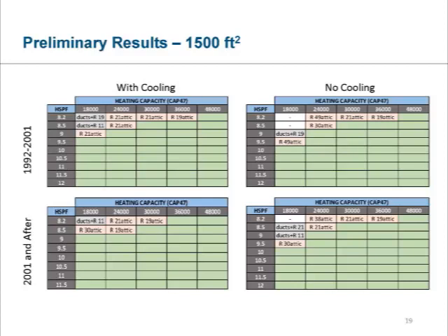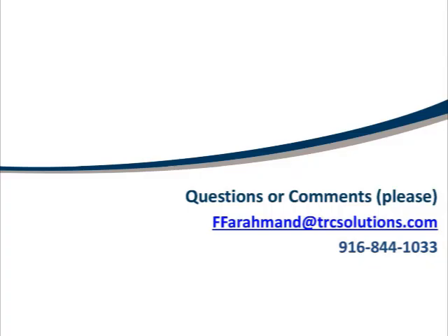It's like 90% of the industry is skipping calculations, and it's a big issue. Oversizing is very, very common, and the airflow is impacted, indoor air quality is impacted, and we end up with tighter and tighter homes. There's a health issue with not properly sizing these systems. I agree. And you get short cycles on things when they're oversized, unless you use a heat pump, which can just go very efficiently.